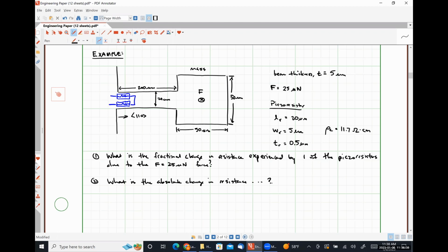That being said, the resistance of the device depends on that thickness due to its cross-sectional area and all that kind of stuff. And so as the resistance goes up, since this is a piezoresistor, it is inherently a thermal noise generator. So the larger the resistance that we implement, the larger the noise our device generates. So there are trade-offs there as well, okay?